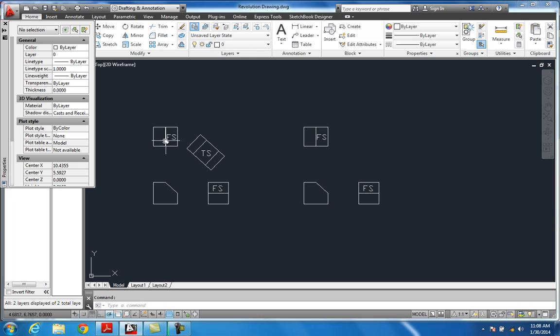On the left hand side here, you've got your top, front, and right side, and it's showing this object. It's foreshortened there on the right side view. So this right here is a primary auxiliary. This is our true edge, a true length of our edge view. And then I projected it up here. I just did a plane method to do this one. I come up and of course project straight off that. These lines have to be parallel with this, and of course there it is. It just projects up. You've got your true surface, the true shape of that, and these areas are foreshortened here.